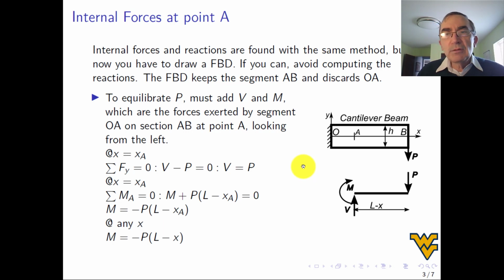In this case, I choose to eliminate OA because that way I don't have to compute the reactions. You'll say, well, but you already computed the reaction. Never mind. Suppose that you asked me to calculate internal forces, and I am in an exam and I'm pressed for time, and the only thing I need are internal forces. So I'm not going to fool around with reactions if I can, all right? Not always I can do that, but in this case I can. I just eliminate this part so I don't see the reactions. All I see are the internal forces, okay?